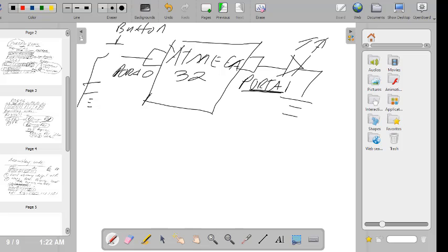It's an output port because whenever we want this LED to light up, it means that this port A1 should give out the 5 volts to the LED. So this becomes an output port. So that's the reason why these ports, you need to configure them either as input ports or as output ports, because then you need this to understand that.